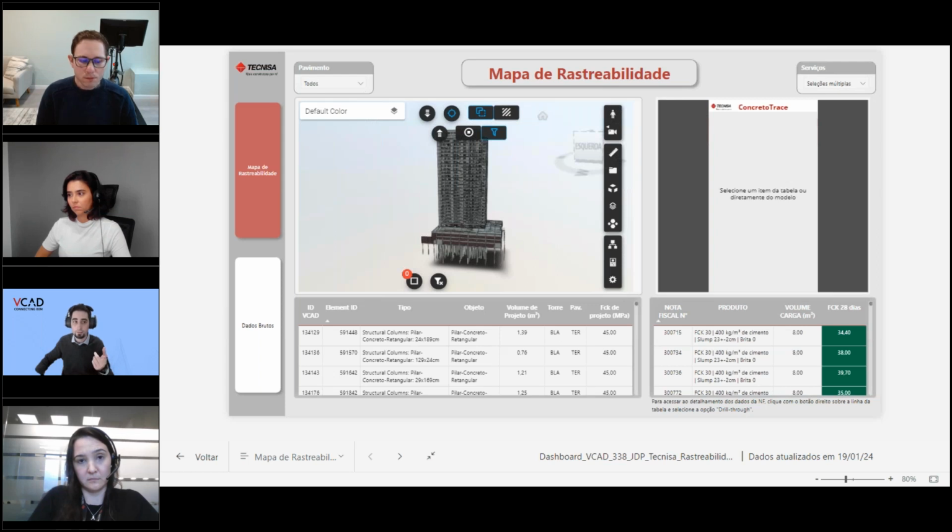Well, Ana kind of touched upon that before. I'm going to give you my 2 cents. It technically is possible to do something like this. It kind of depends on what the model looks like. As Ana was mentioning, it would require you to federate the model beforehand, which if it's a big model becomes kind of cumbersome. That's the one thing I would keep in mind. Usually for large projects, we tend to suggest using Navisworks because that's where you get the best performance, without any doubt.